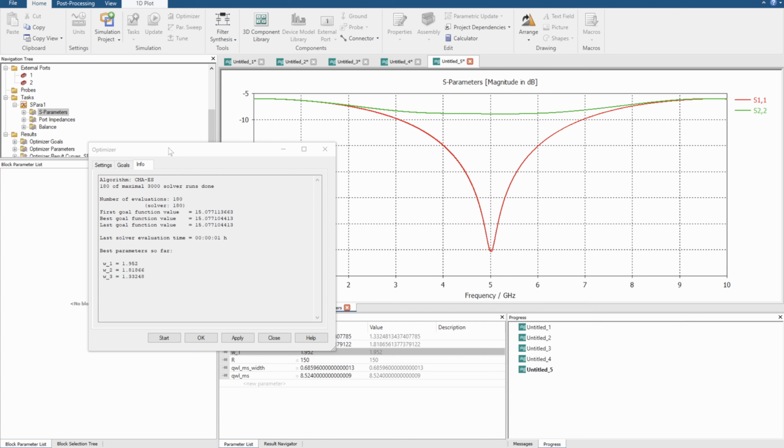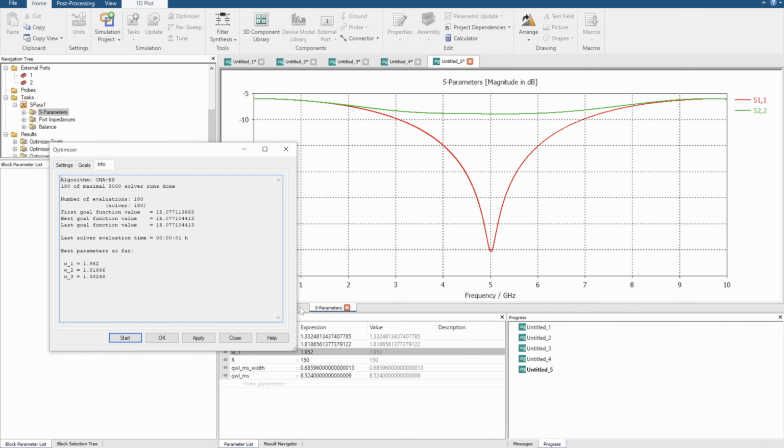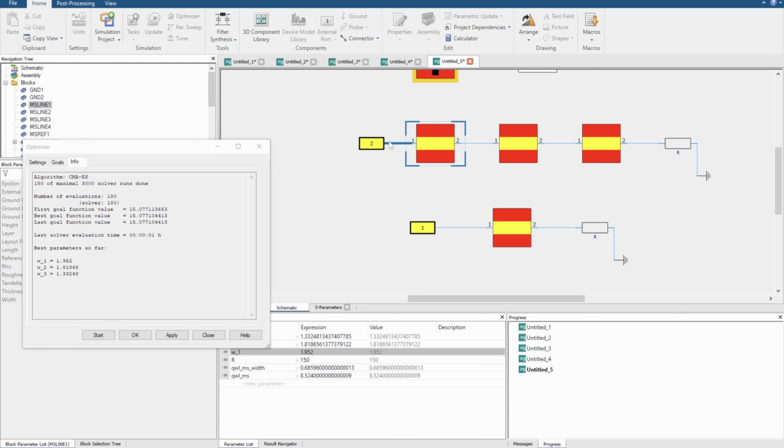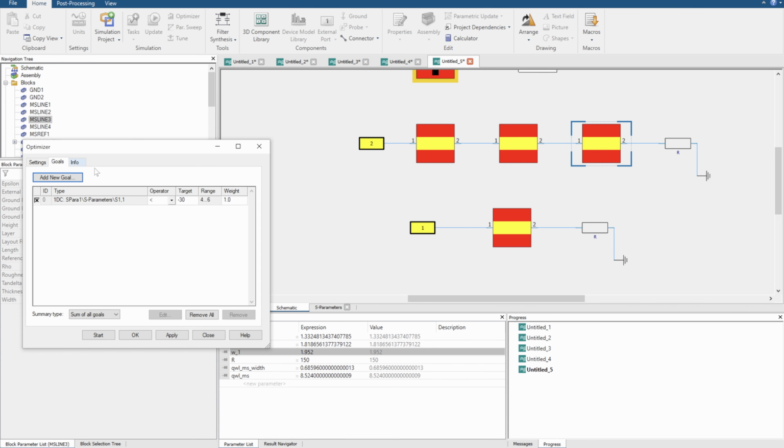Okay, and we can just from inspection looking at it, the first one was 1.95, so it matched it to 50, where we know it shouldn't have. It needs to be a lower value actually. And then these 2 points, we can kind of see the stepping down nature. And so it's going a high, 50 ohms, and this might be 75 and this might be 100. So it's getting the correct kind of nature of how it should look.